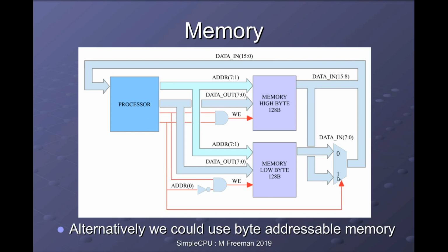So when that address line is a 0, you'll select the 8 bits from the low memory, and when it's a 1, you'll select the 8 bits from the high memory. And that 8-bit value is routed through the processor and stored into the accumulator. Finally, we need to be able to access a 16-bit instruction in one memory transaction. And again, that is possible with this architecture.